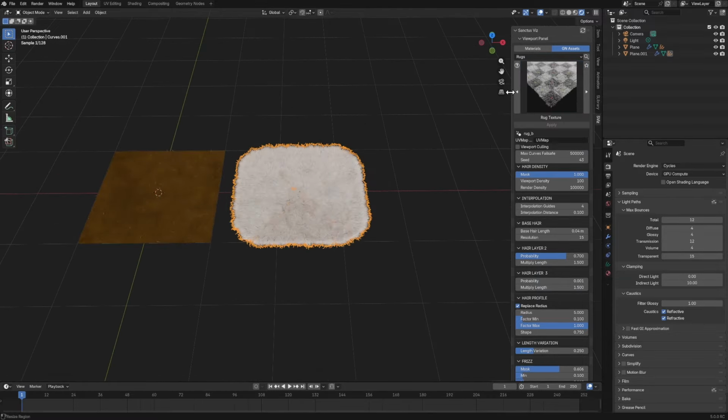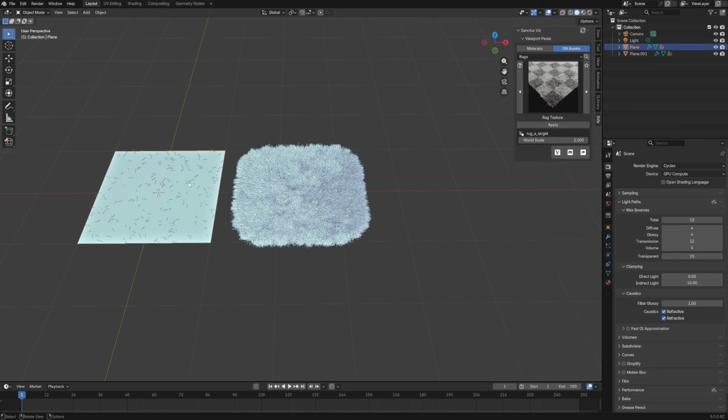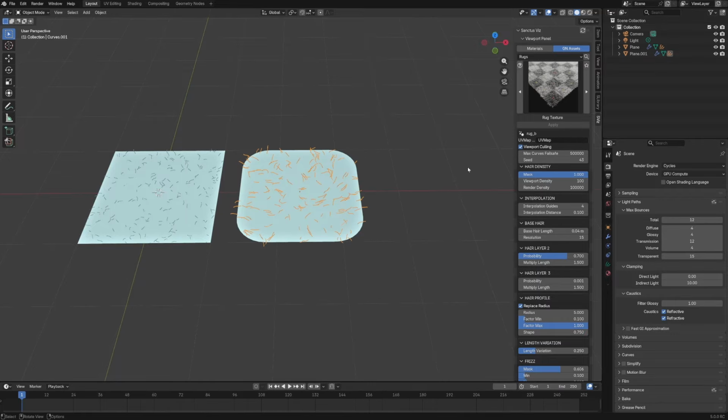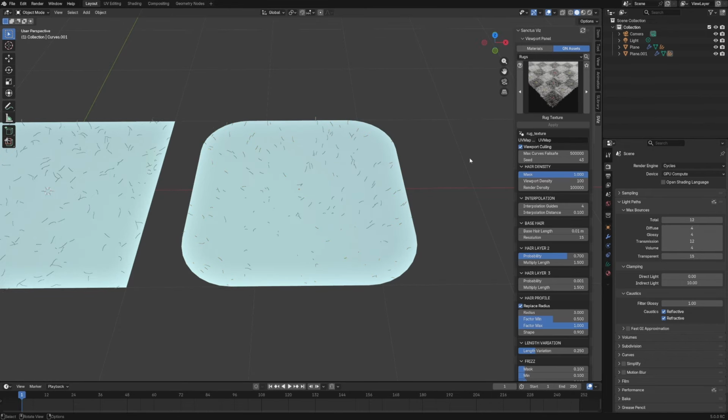In this case, this specific asset already has what I mentioned, that it can replace one, but you have to target the base object, not the particles. So in this case, I'm going to select the base, and apply this different one. It will prompt if I want to replace it. I can replace it.